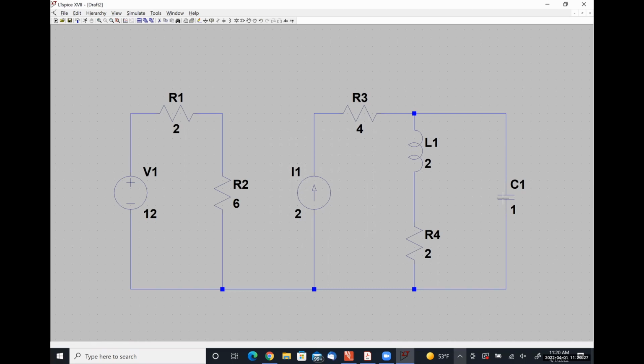Is this what my circuit looks like with the switch open, so that we're during the transient condition, yay or nay? So that's a fantastic question. Our simulation is not going to be just for the moment in time t equals 0 plus. It's going to be for all points in time t equals 0 plus and beyond, which is why we can't model our inductor as just a current source, because we're including points in time where it isn't behaving like a current source.